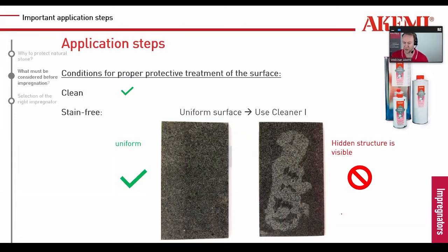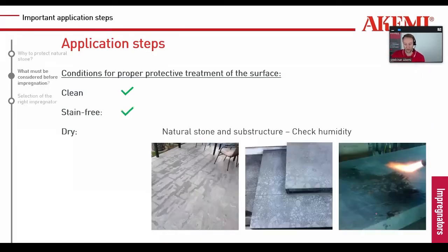Of course, the stone must be dry before we use an impregnator or penetrating sealer. And not only the stone itself, but also its substructure when it comes to outdoor terraces, for example. When it's like 3 days after heavy rains, of course the stone looks dry on the surface, but underneath there could still be some humidity. So here you have to check if the stone is dry.